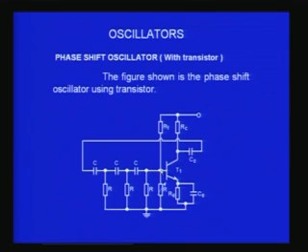So between this base, which is the actual input of the amplifier, and the collector, there is a 180 degree phase shift we have already seen, and that 180 degree phase shifted voltage is applied here. With this combination of RC, RC, RC, you try to produce another 180 degrees, so that totally it becomes 360 degrees, and then this voltage which comes from the output becomes in phase with the input that you perhaps gave at the beginning. You have not given anything, this happens very fast.